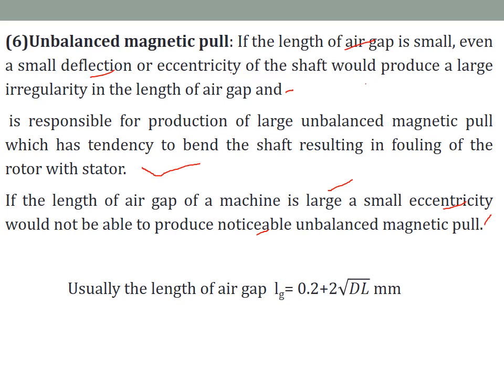So finally, there is an empirical formula to calculate the length of the air gap. Lg is equal to 0.2 plus 2 into the root of D into L mm. This is Lg in terms of